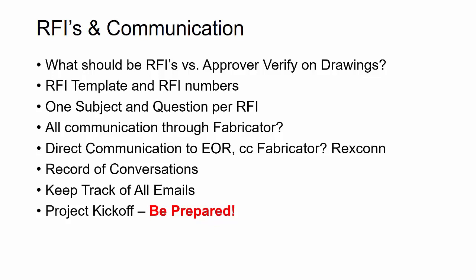Best thing I can say is, buy yourself some time, get a couple days, get familiar with the job, start looking at the RFIs, start to understand exactly how you're going to do the job and what you need to get from the fabricator, and be prepared when you go to the kickoff. So when you get there, you can get as much of the information during that kickoff versus writing lots of RFIs after the kickoff.